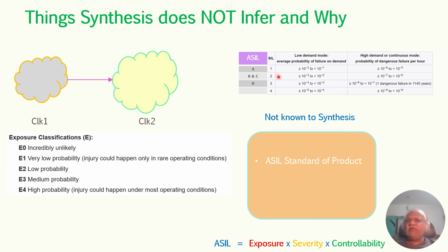This is based on the safety integrity level, and this automotive safety integrity level is slightly different. Their nomenclature is also different, and roughly we can map it in this fashion. There is nothing for 4. So here, the ASIL failure rate itself is very, very low for the worst case, like D. What does this failure rate mean? When we have observed the MTBF, the inverse of MTBF is the failure rate.